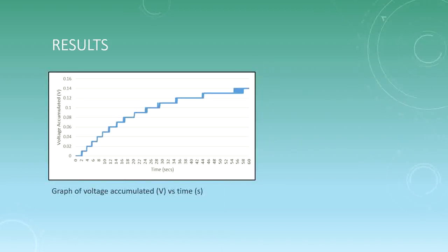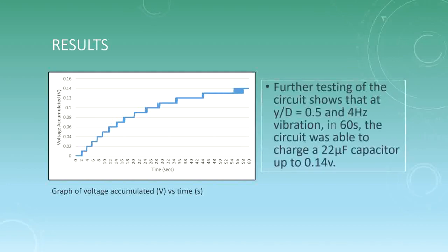Further testing was done, including a capacitor in the circuit. This graph shows the voltage accumulated versus time. In 60 seconds, at vibration characteristics of y/d equal to 0.5 and 4 Hz of frequency, the circuit was able to charge a 22 microfarad capacitor up to 0.14 volts.